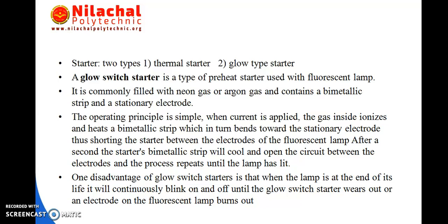One disadvantage of the glow type starter is that when the lamp is at the end of its life, it will continuously blink on and off until the glow starter wears out or an electrode on the fluorescent lamp is burnt out. This is the thing about a starter. We generally use a glow type starter. The operation is the same: when current is applied to the gas inside, the heat bends the strip.